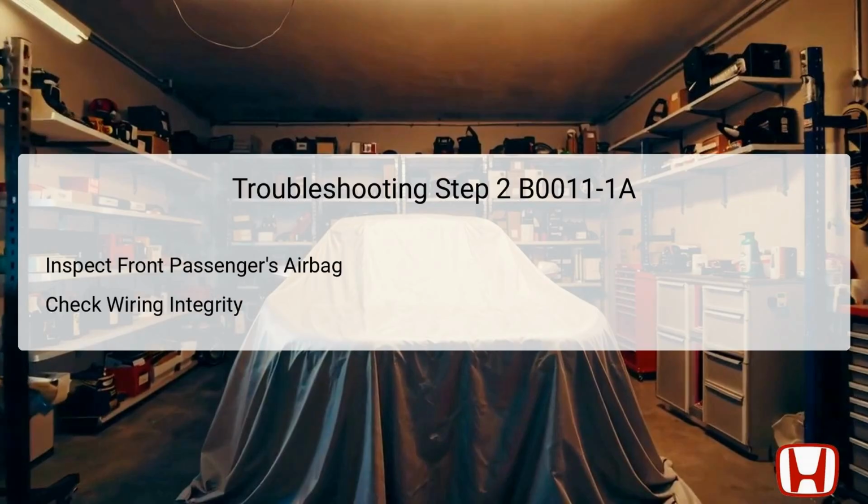In this step, the front passenger's airbag must be inspected for faults. Start by verifying that the airbag inflator connector is disconnected to prevent any unintended deployment. Then, using the SRS Simulator Lead J, connect it to the front passenger's airbag inflator connector.